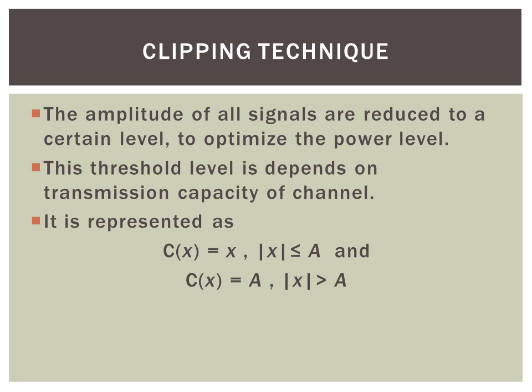The drawback of this technique is the loss of data, because as we are clipping the amplitude, that clipped part is removed from the transmission, so that much data is not available at the receiver. This is a big drawback. Only when the amplitude difference between two carriers is small is this technique suitable.